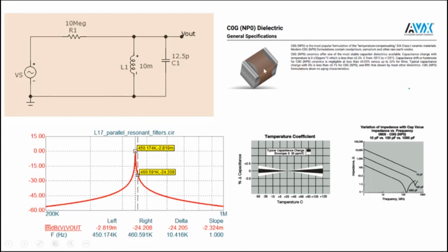So in this case, if you pick up a capacitor and you measure its impedance as a function of frequency, you should get a straight line. This is a log-log plot. If you plot log of impedance versus log of frequency, you should get a straight line. You do get it. It acts like ideal over this range, but note that here is where there's a shift. It's no longer capacitive, but at this point the impedance is actually falling to 0 and then becoming inductive here. And here also it is going from capacitive to inductive.